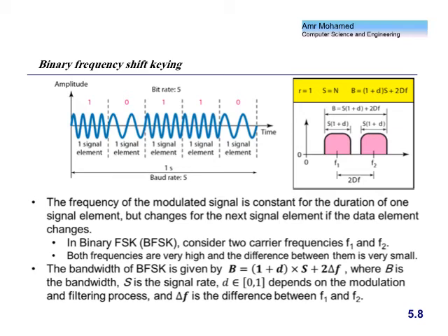Okay, because if I have some type of noise, like, for example, thermal noise or impulse noise or something like that, these types of noises actually change the shape of the signal, not only the amplitude. Changing the shape means changing the frequency components of the signal. So if the frequency components of the signal are very close to each other, it's going to be very tricky for the receiver to recognize one from the other. In other words, I have to have some separation between those two signals in the frequency domain as much as possible.